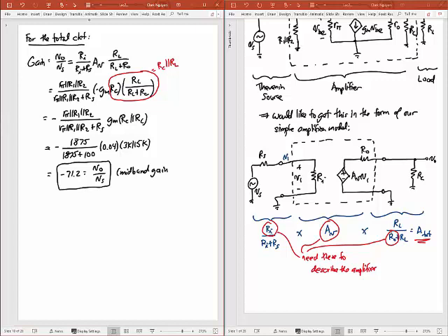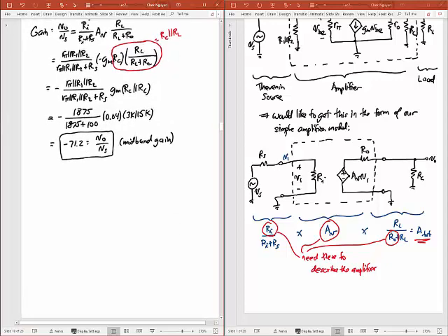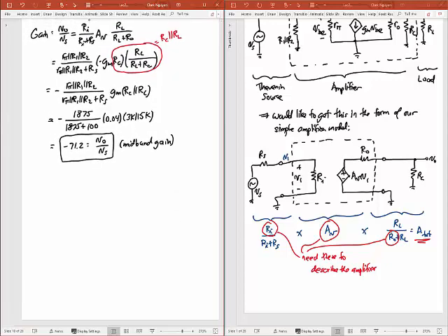So that's my midband gain. So that's excluding the effects of roll-off due to capacitors that we'll talk about a little later on. Okay, so that's the total gain of this. And so you can use this same technique to get the gain from any point to any point on this amplifier. So right now we're talking about the gain from the input to the output because that's usually what we care about. But I can also say, just for kicks,